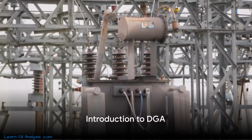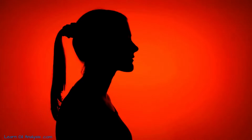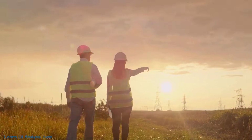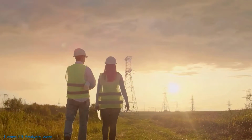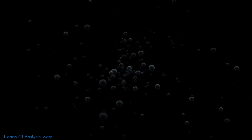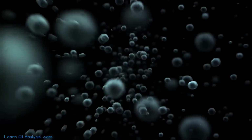Dissolved gas analysis, or DGA, is a technique that's been saving the day for electrical engineers worldwide for decades. You see, transformers are secretly communicating with us through the gases they produce. They can tell us when they're not feeling well. DGA is the tool that helps us hear these whispers. It's all about understanding the gases dissolved in transformer oil. The presence of certain gases can indicate specific faults, helping us to nip potential issues in the bud, saving money.